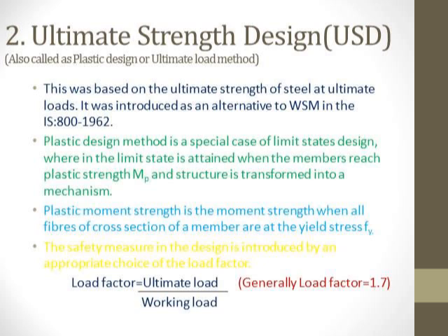The safety measure in the design is introduced by an appropriate choice of the load factor, and the load factor is equal to ultimate load divided by working load. Generally the load factor is assumed to be 1.7.